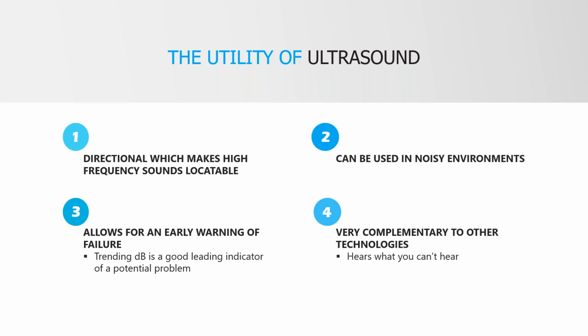And then ultrasound, aside from being the most versatile of all the condition monitoring technologies, is also very complementary to those other technologies. Just like an infrared camera sees what you can't see, an accelerometer feels what you can't feel, ultrasound hears what you can't hear. So again, it's just another extension of one of our senses, and it's another tool that we can use to hopefully gather as much information as we can to make a good diagnosis on what the health of that asset is. So again, very complementary to anything that you may currently be doing in regards to infrared thermography or vibration analysis.